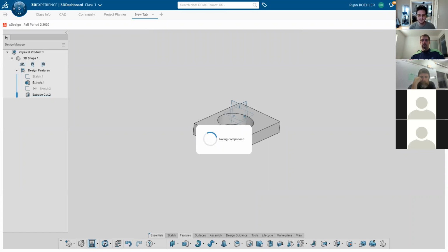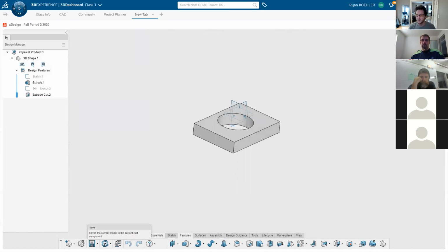The reason is temporary data. If we did autosave, that consumes a ton of temporary data because you need to be able to undo a good amount of times. With an autosave, it usually creates a generic number of undos, like 10 or something. If we do save points, it actually allows us to undo between save points as long as you have it open.